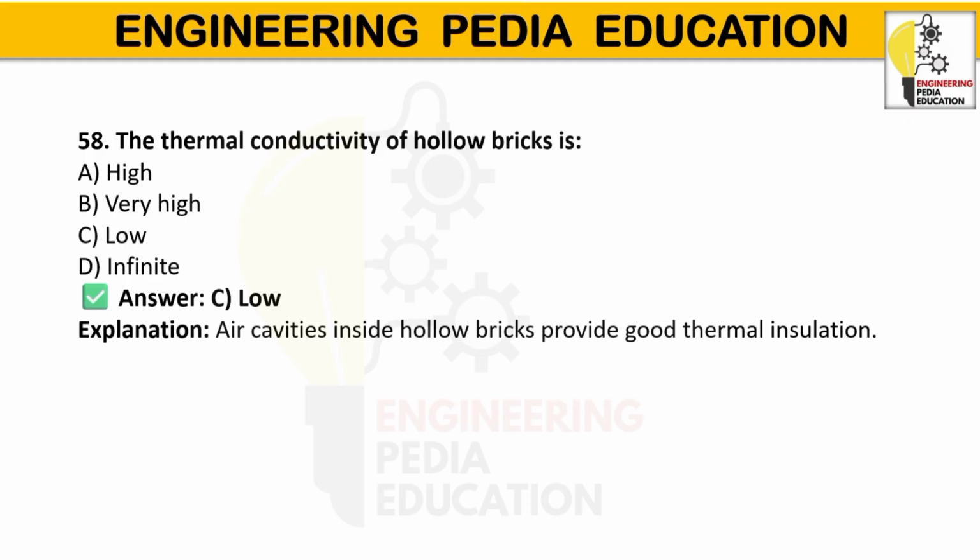Hollow bricks are bricks that have pores present in them. Their characteristics are light weight, good thermal insulation, and good sound insulation. Construction is faster due to lower dead load, and lower material consumption is also there in this type of brick. Uses are partition walls, non-load bearing walls, and multi-storey buildings. Advantages are reduced structural load, better heat and sound insulation, and economical transportation.